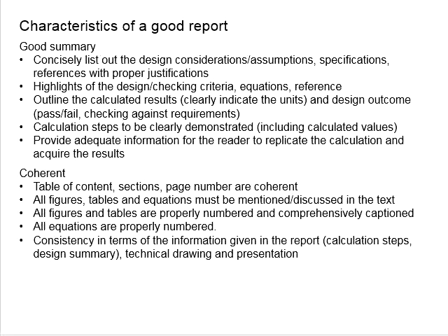You should also list out the specifications and details which you're going to adopt during the design calculations later. These include the values used, such as the properties of the materials, the loading that you analyze, as well as the equations that you use, and so on. You should also provide a good reference for every single item which you have obtained from the code of practice, such as Eurocode 1 and Eurocode 2.